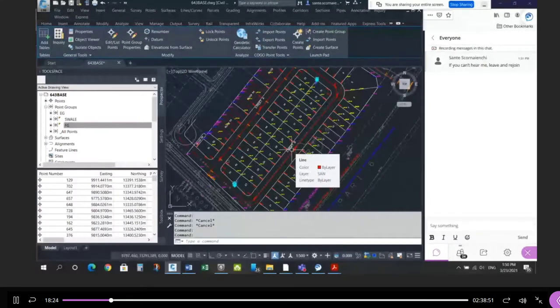Remember, these 2 elevations come from the corridor model. So if the profiles are wrong, the corridor is going to be wrong, the corridor model surface is going to be wrong, and then these 2 elevations are going to get the wrong vertical data. Okay, so these didn't have to be perfect, but they had to be close. Otherwise, you wouldn't be able to design the backyard the way I described it to you in the PDF.